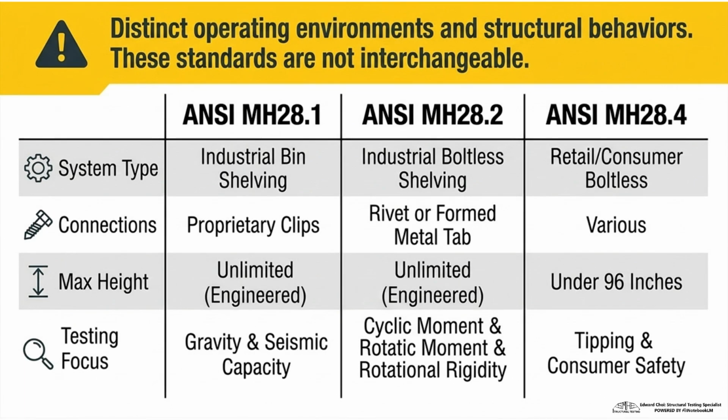One point must be stated clearly. MH28.1, MH28.2, and MH28.4 are not interchangeable. MH28.1 applies to industrial bin shelving, proprietary clip connections, gravity and seismic capacity. No prescribed height limit when engineered.